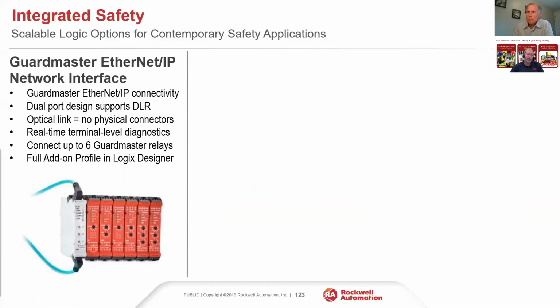But these particular relays, these GSR relays, are universal input type devices. Any standard inputs will go in there. 2 normally closed, OSSDs, 1 normally closed, etc., all those kind of things. And there are different versions. There's about 8 part numbers now, I believe, maybe 9 at most. But those 8 or 9 part numbers take the place of hundreds of part numbers prior in the safety catalogs that we used to print. So it's a very, very scalable solution that has a lot of different application depending on what your needs are.